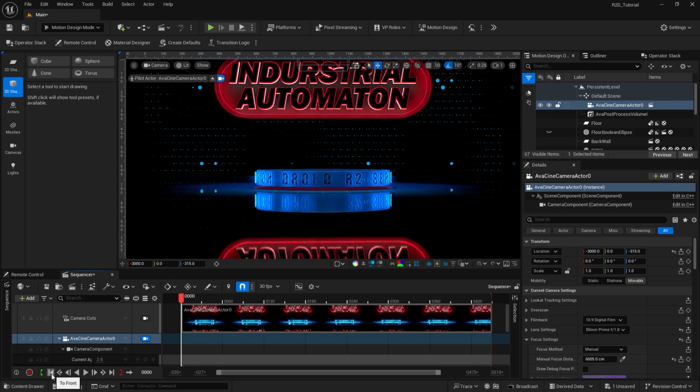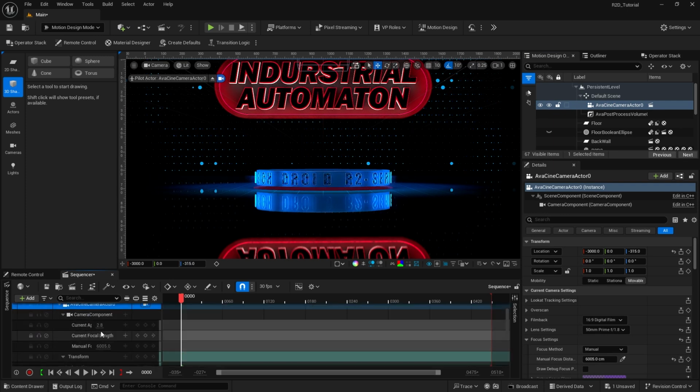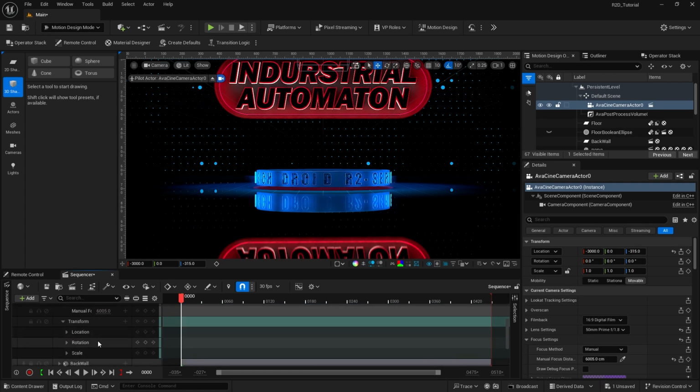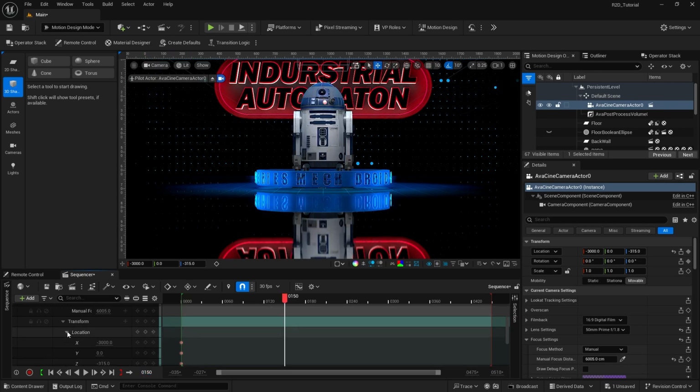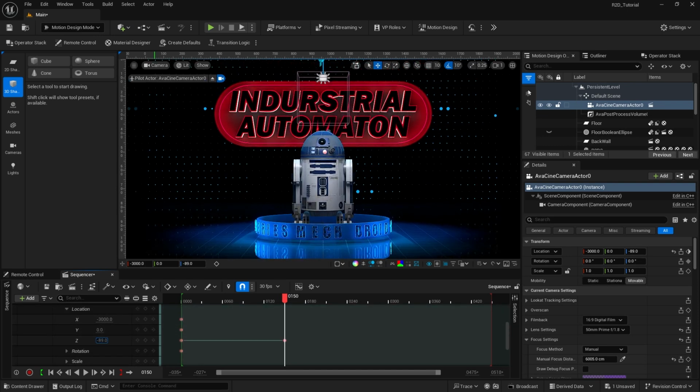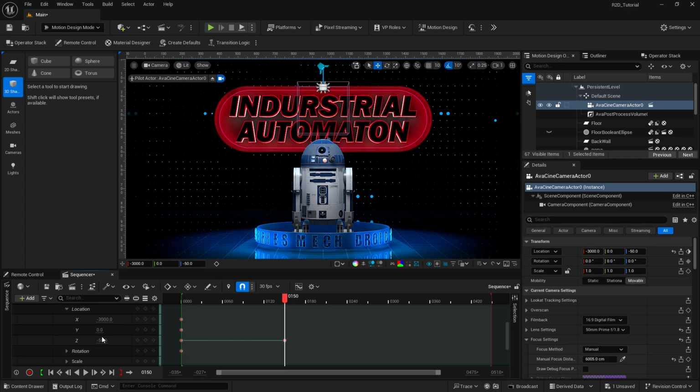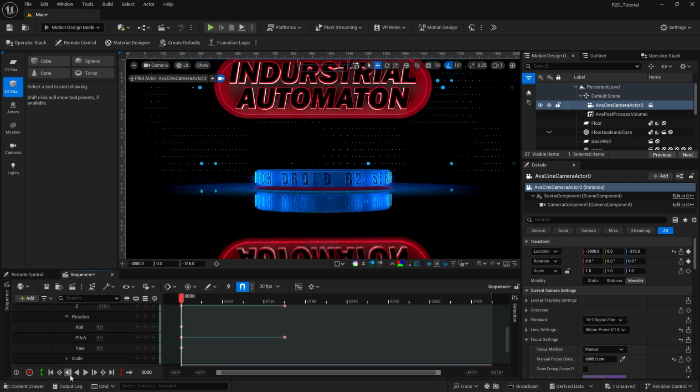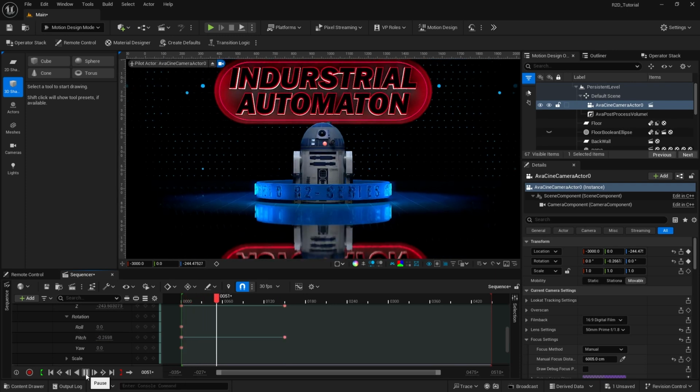I'm going to jump back to the beginning of the timeline right there, and I'm going to jump down into the transform properties for this, and I'm going to use location and rotation on it. So I'll set keyframes for that, for both of those. And I did a 5-second animation on this, so I'll jump to 150 frames in the sequence, and I'll go into the location properties, and I'll bring that up a good bit, set that to a negative 50, and then I'll rotate it just slightly. We can go back to the beginning of the timeline and watch this animation.